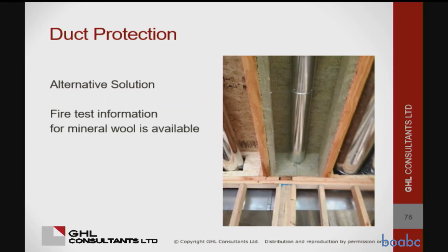Or we do this, which is much easier to install. There are a couple of tested wall assemblies where they fastened this semi-rigid Rockwool Comfortboard to the studs and fire tested it under the S101 test. And they got an hour out of a wall that had literally no gypsum board on it. All it had was studs and Comfortboard. So this stuff's magic.